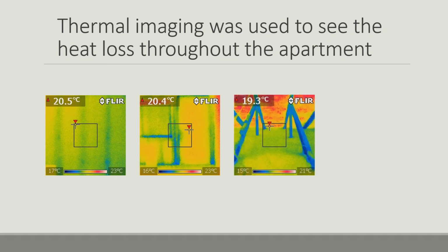This image was very interesting to us because it shows the temperature differences in the attic. The blue are the attic supports, greenish yellow is the loose fill insulation, and the red is actually the plywood on the roof. We initially thought the insulation would be giving off more heat than the plywood, however the thermal image camera showed us the opposite.